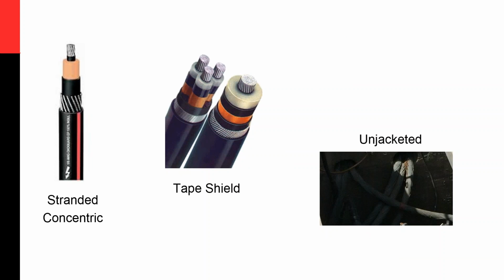As I said, on the left you can see the wires, actual wires. Then you have the tape in the middle, and the unjacketed cable. I only found a picture, not so much an illustration. And what you see there, this gray, this is the corrosion of the actual neutral. And this stuff can actually corrode away. It can be literally eaten away by the elements, by chemical reactions in the soil, and that can cause problems.